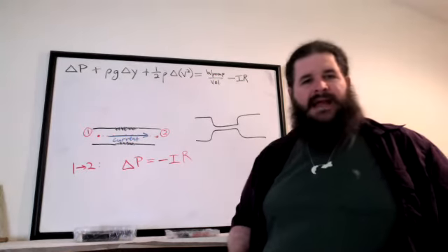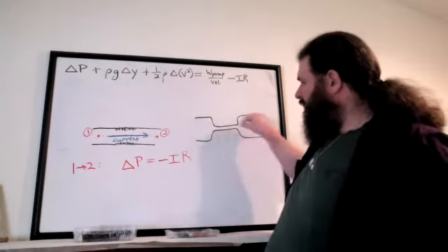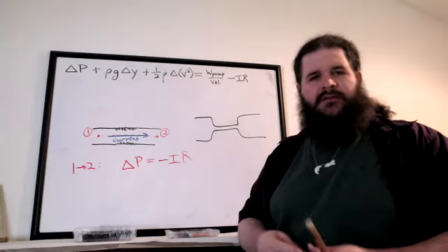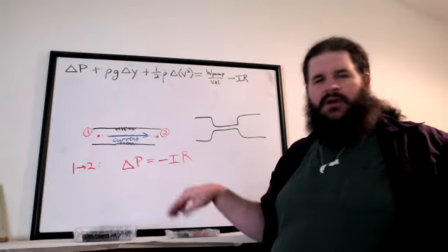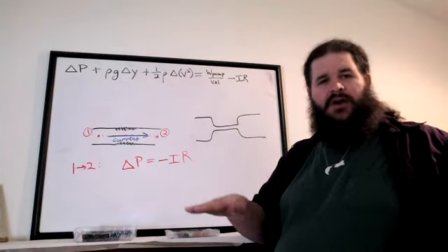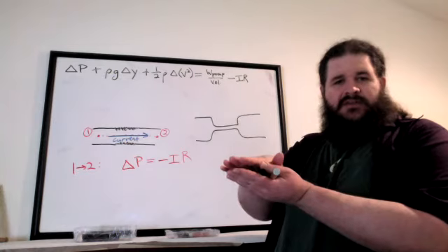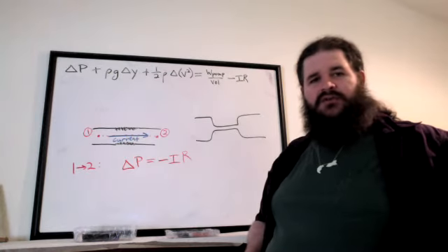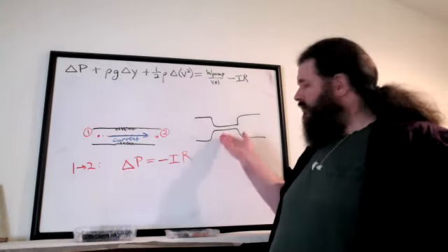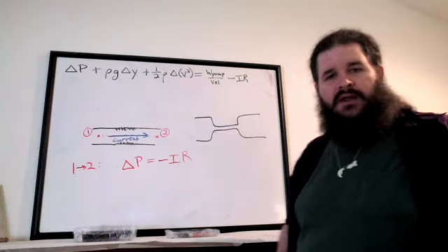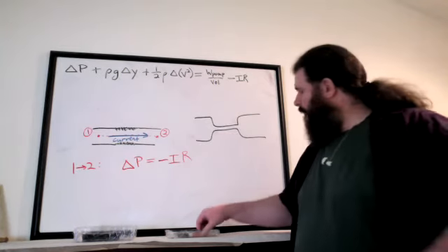Usually the way you make a pipe have very large resistance is you make a narrower zone. Like for instance, if you got water flowing through a garden hose and you step on the hose, you're pinching it mostly flat. You're going to reduce the flow to a trickle because there's so much resistance in this narrow zone that it makes it difficult to flow.